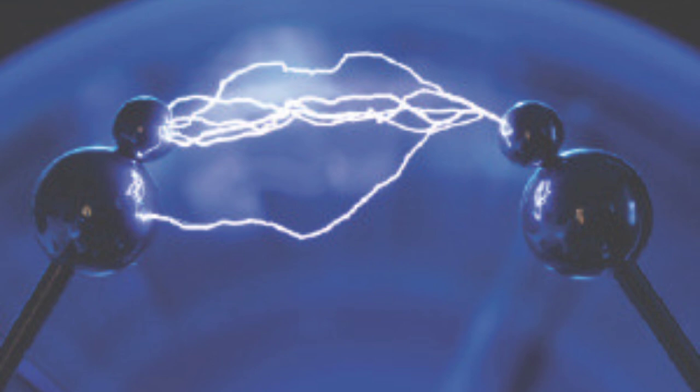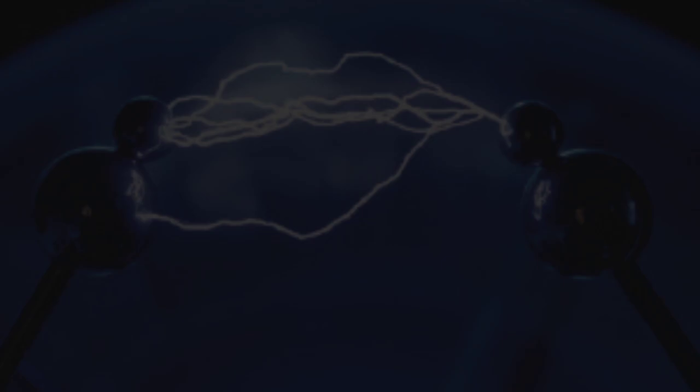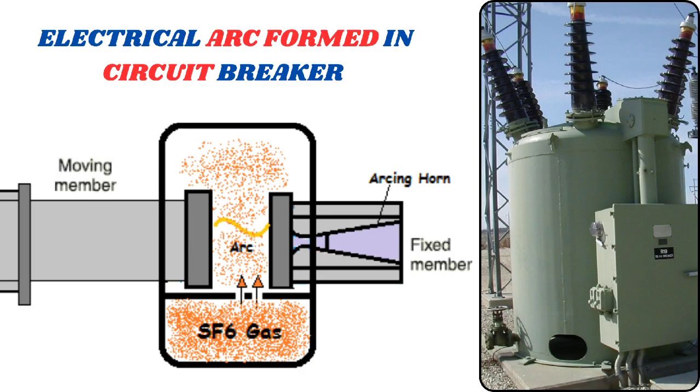It is important to know that every medium such as air, vacuum, or oil can be ionized and form a conducting path at very high voltage. At such high voltage the medium loses its insulation properties and behaves like a virtual conductor. In circuit breakers this medium serves as the arc quenching medium.